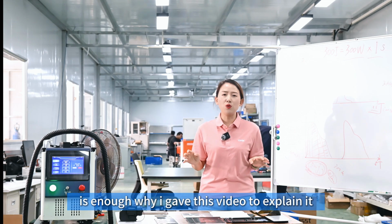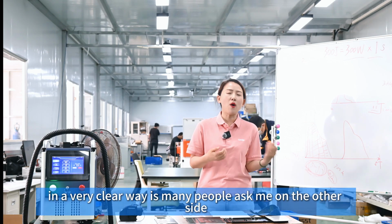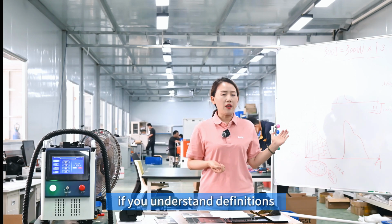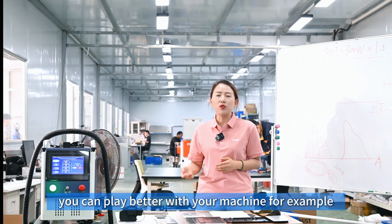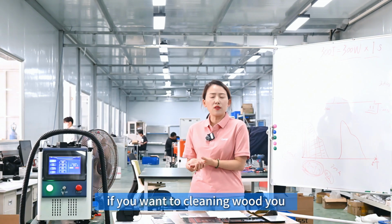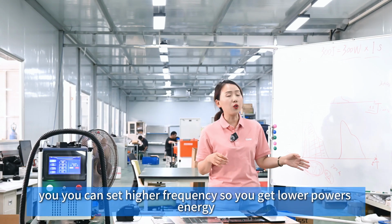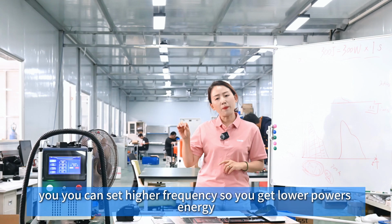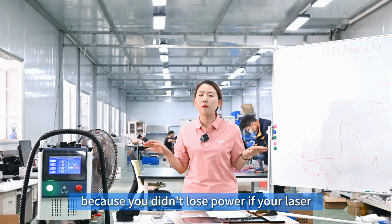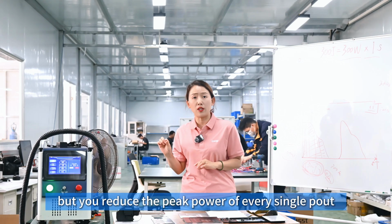Why I made this video to explain it in a very clear way is that many people ask me. And on the other side, if you understand these definitions, you can play better with your machine. For example, if you want to clean wood, you can set a higher frequency, so you get lower pulse energy, but you get the maximum speed because you didn't lose power of your laser, but you reduce the peak power of every single pulse.